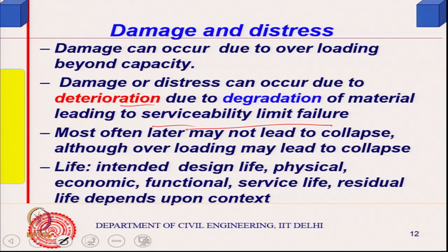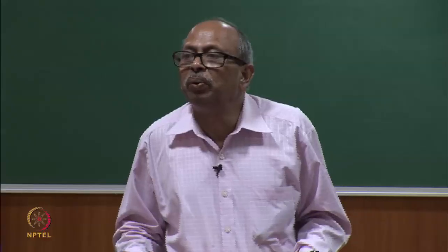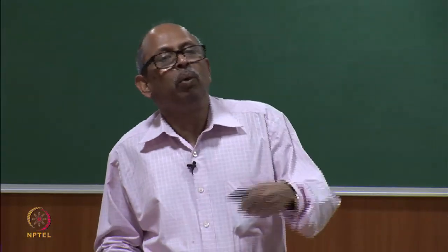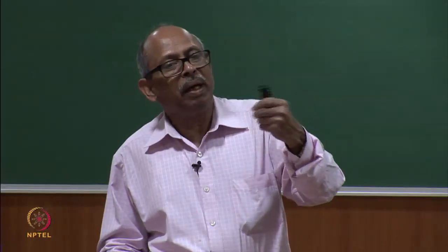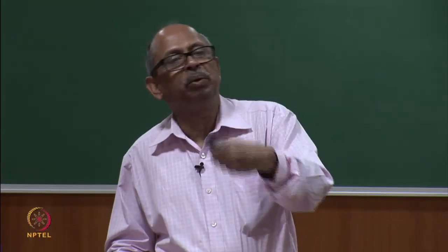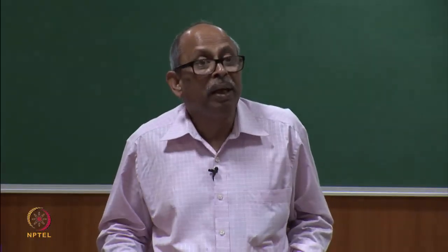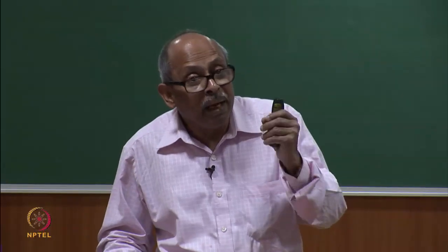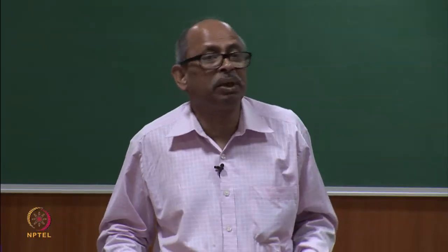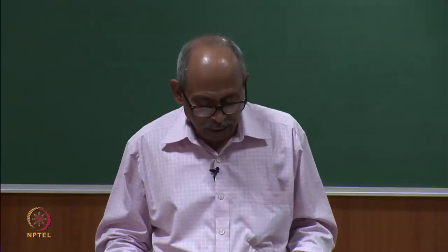I have already talked about intended design life, physical, economic, service life, and there is one more terminology, residual life. Residual life means at this moment part of the life is over. At the mid of intended design life, I want to look into how much life is left, in any context, could be residual service life. We expect this is the period during which it will remain in service from this point of time. Residual life, because some damage has occurred. So, the time for the next repair in terms of residual service life of the element, that you have to see. So, that is what it is.